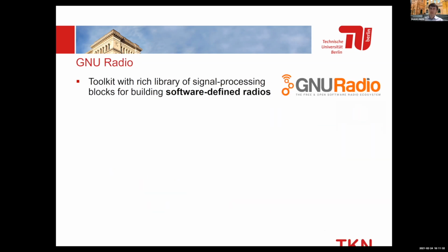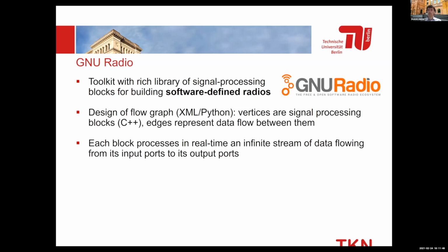The other framework we used in our work is GNU Radio. I think you also heard about that. It's a rich toolkit which allows you to build software-defined radios. Basically, you design a flow graph where the vertices are signal processing blocks written in C++, and you wire them with each other, and then you have some data flowing over the edges, and each block processes the input data in real time and creates some output data.